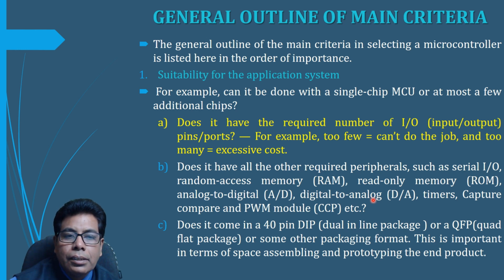This will determine the suitability of the microcontroller for the application, because if your application needs more input output pins or ports, then it will not be able to run on a microcontroller which has a limited number of pins. So too few can't do the job and too many will be excessive cost.